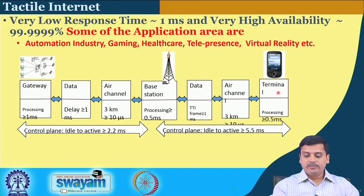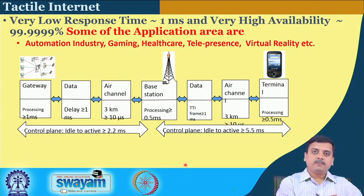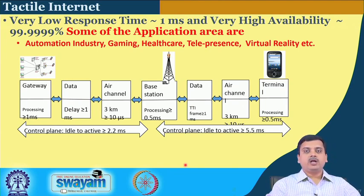You need to reduce the propagation time, you need to reduce the processing time, and hence in turn you need to reduce the TTIs, or in other words the frame duration, which would result in changing of the symbol duration, and if the symbol duration changes, that would result in a significant growth of the bandwidth. So, that means if you have to make symbol duration smaller, the bandwidth would become larger. If the bandwidth occupied by the signal becomes larger, then the effects of multipath fading would come in. That would mean that what was previously experiencing flat fading condition, and the receivers were designed to operate in a very simple manner, would now have to be completely changed.